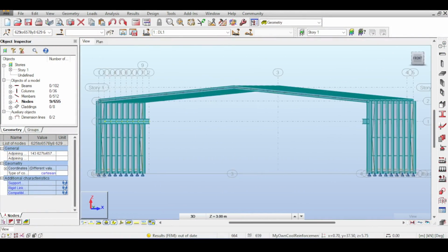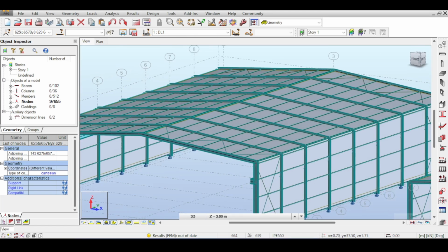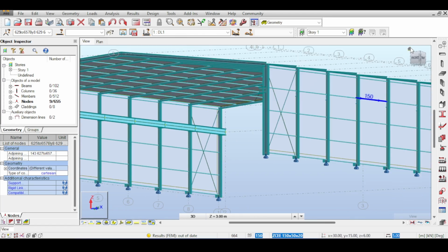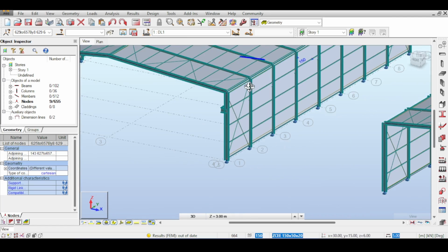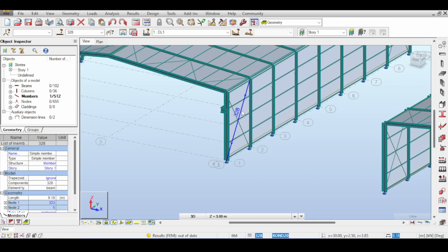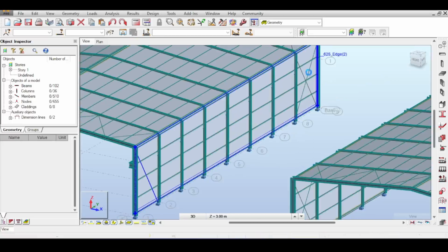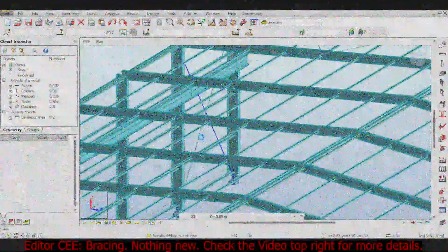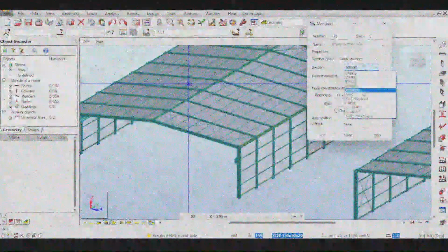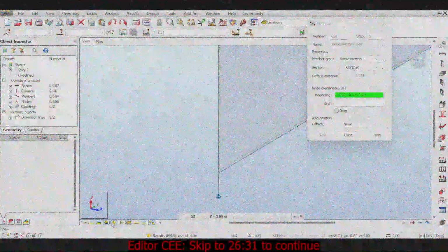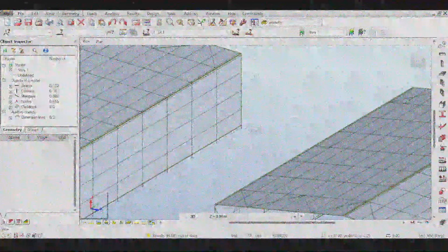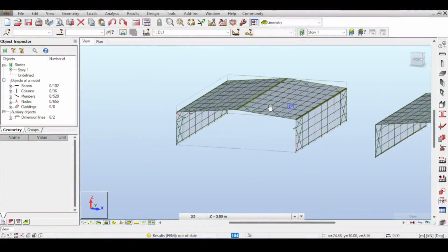What else remains? Well, what remains is to brace. Because my bracings now are incorrect, according to the reference, I should brace now at 2 points, one bracing for the runway and one bracing for the rest. So I'll do it with an X bracing and a V bracing or something. So yeah, that's the runway beam. So I prepared this for the runway beam.